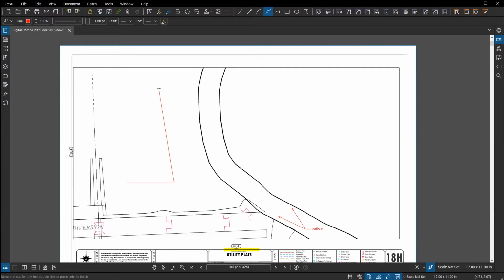A certain path like polyline or the perimeter shape being drawn in by a polygon or area. Just hit backspace. It'll remove those last points. And you can go all the way back to where you first started the tools. Click your way through. Go, oh, darn it, not that one. Go back, back, back, and then choose the path that you actually wanted instead. Put all the path along that.